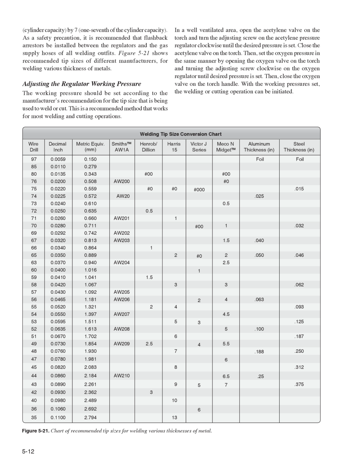Figure 522, neutral flame. The neutral flame burns at approximately 5,850 degrees Fahrenheit at the tip of the inner luminous cone and is produced by a balanced mixture of acetylene and oxygen supplied by the torch. The neutral flame is used for most welding because it does not alter the composition of the base metal. When using this flame on steel, the molten metal puddle is quiet and clear, and the metal flows to give a thoroughly fused weld without burning or sparking.